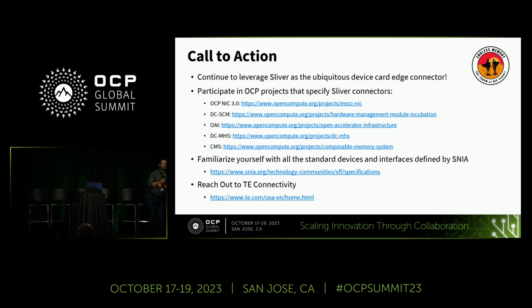Another one is, of course, direct attached things are what we do today. And for that, maybe a x16 connector is good enough. But you've seen a lot of wonderful pictures that talk about many things, memory pooling and other things that CXL is enabling. For that, we need a little bit better density. Card edge might still be good, but we might need to have multiple layers of it or such. A card like PMM might be appropriate today for one direct attach, but if it wants to support memory pooling, it needs more SerDes.